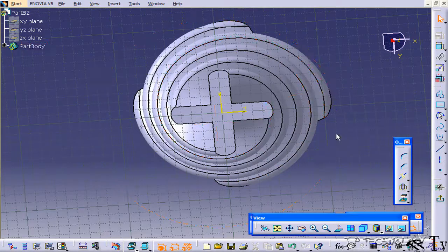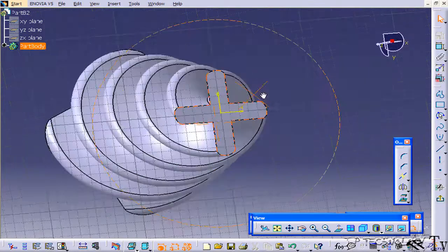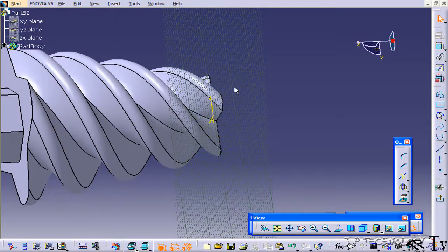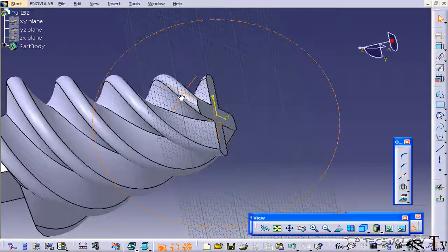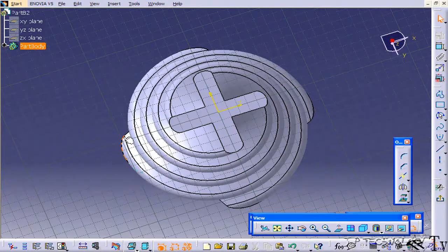So to do this, you have a whole set of projection tools. If you look here on the toolbar, you have all these projection tools, and the one I'm going to use the most here is the Project 3D element. We're going to project a bunch of these lines onto this plane that we're working on, and from those we're able to lock into those points or those edges and draw and make components off of it.